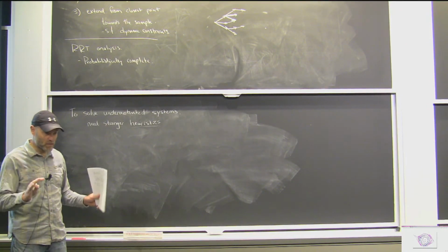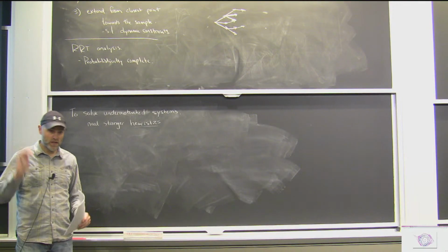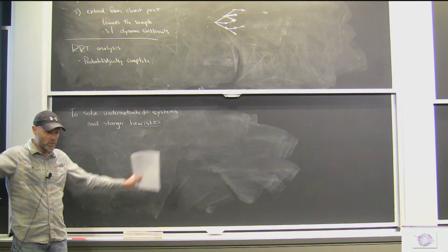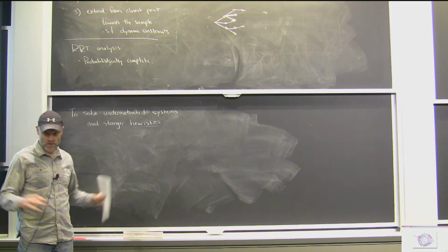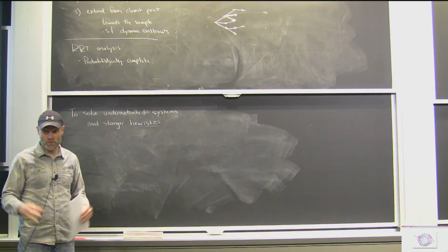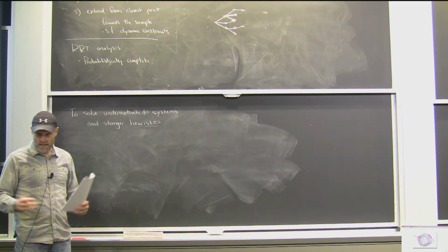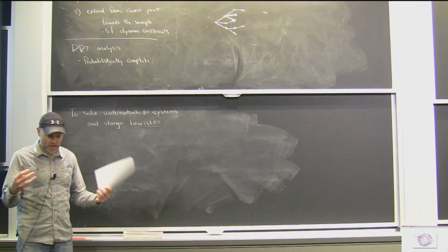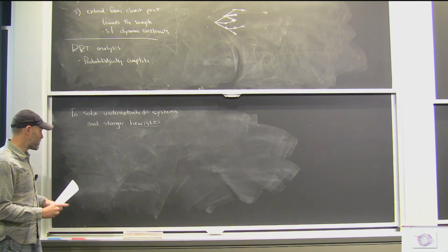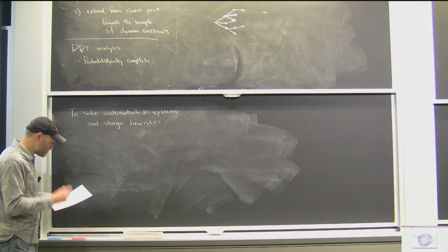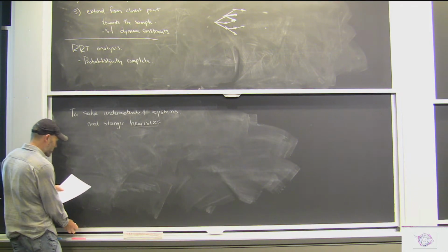We have the couple basic algorithms, the PRM, the RRT. There's a few fundamental improvements on there, but there's just a grab bag of heuristics where people have found different ways to potentially put things together. And I'm optimistic that we're going to continue to understand the right way to do these things. But let me tell you today about a few of the best heuristics.